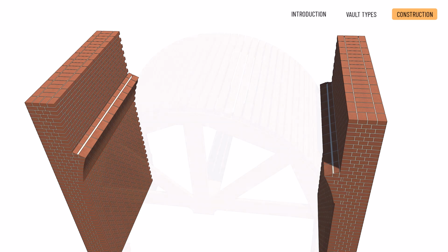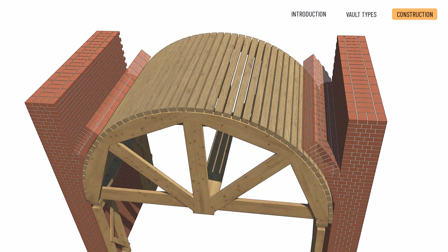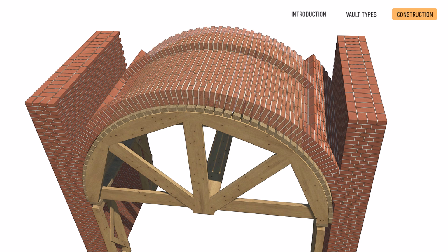4. A template and supporting scaffolding must be prepared for the vault masonry, and the vault has to be made on its surface. 5. When starting, you proceed with the thickness of the whole brick, impost width, in the masonry, following the curvature of the template. 6. In the middle section, the vault can be narrowed to the thickness of half a brick. However, every 1 to 1.5 meters, there will be reinforcing arches, similar to reinforcing walls with pillars.